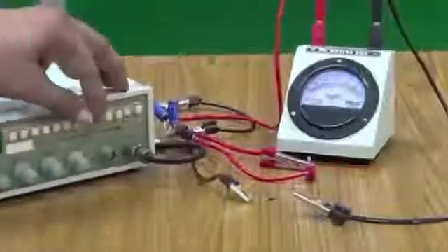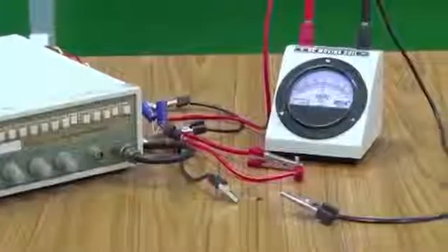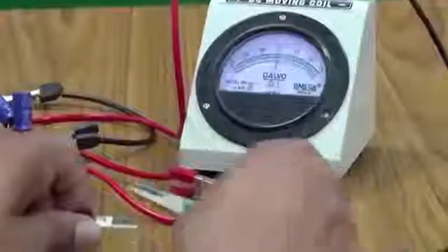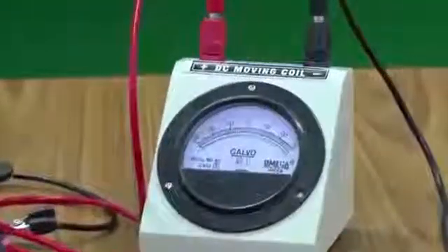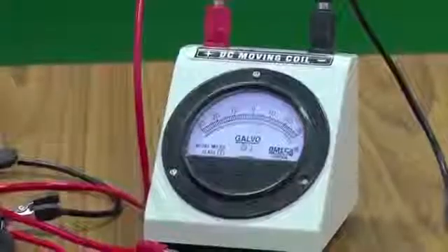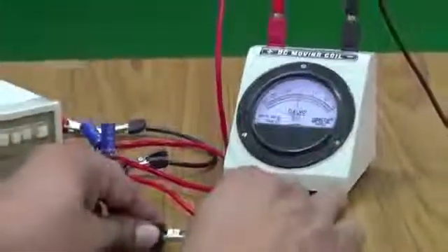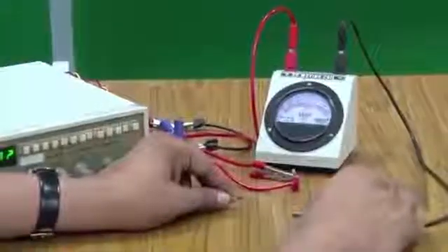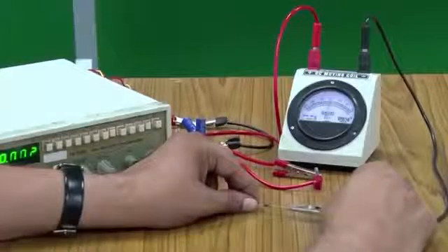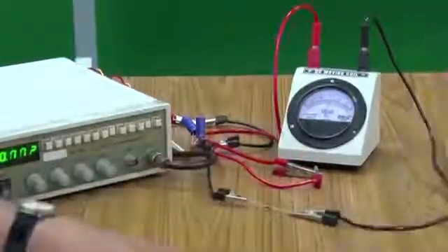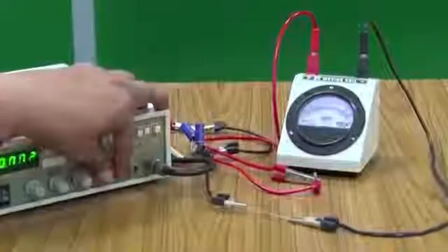If I give a very small voltage, what happens? Let us see. Suppose at this voltage, you do not see any current. But if I remove this diode and I put it here, you can see some current. So, that shows that this assumption that we had taken, that just forward bias and you have large current, is not true. You have to supply some initial voltage, after which that IV characteristic, the exponential part, starts, only then it works. So, let me increase this voltage and you can see that yes, now it has started going.